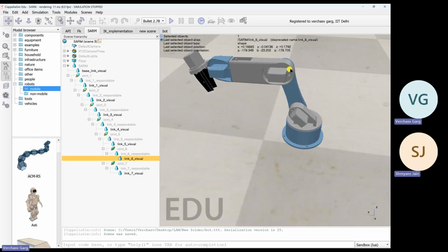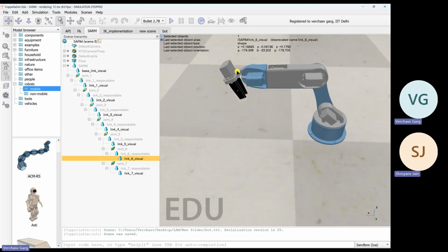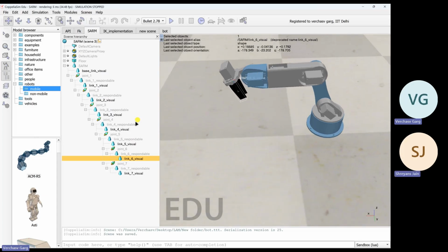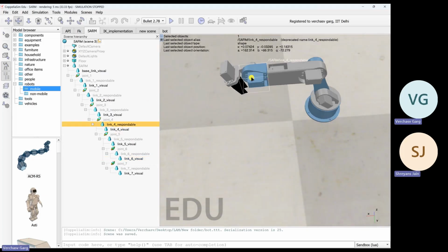Above that lower arm we have another servo motor, that is joint 3. Near the gripper, another arm part provides rotation about the horizontal axis, that is joint 4, and for joint 5 we have a servo motor that provides the rotation of the gripper.